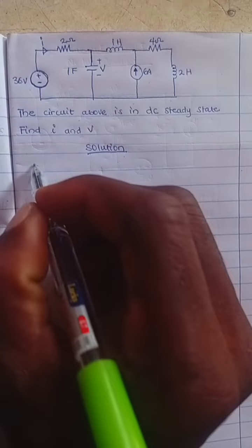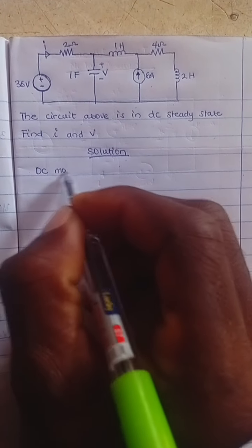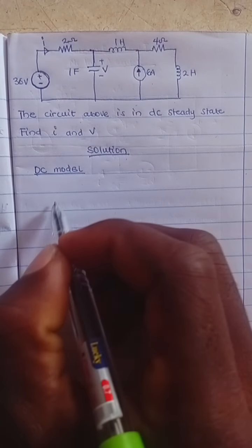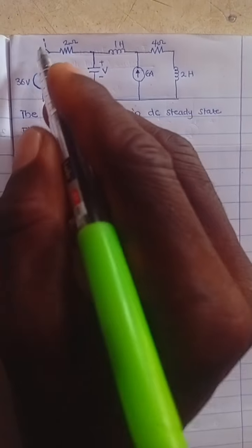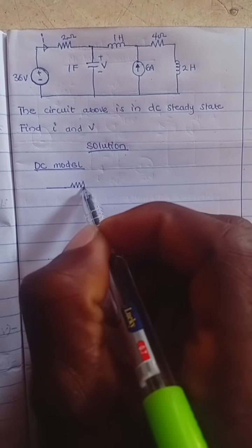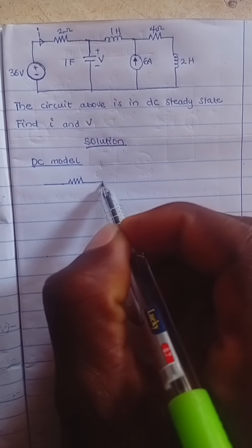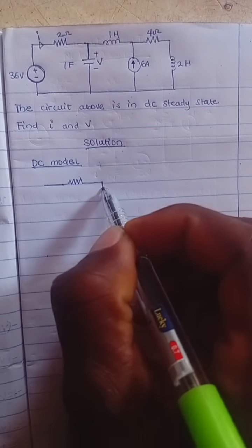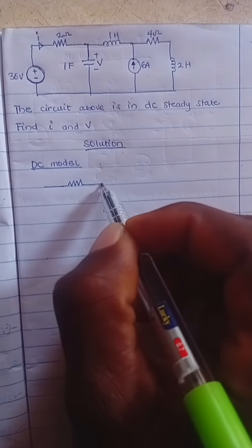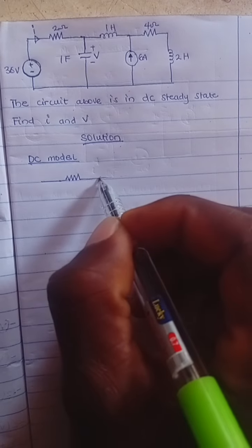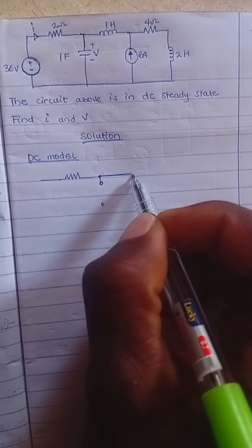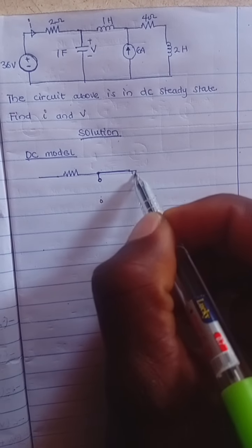This is the DC steady state model. I'm starting from the top, so I'll redraw this circuit. I will have my resistor because the resistor doesn't change. It's just the capacitor and the inductor that change. So this capacitor becomes an open circuit, right? There was originally a capacitor here. Then I should have drawn an inductor, but because we are talking about DC steady state, it becomes a short circuit. So you replace it with a wire, and then you have this current source here,